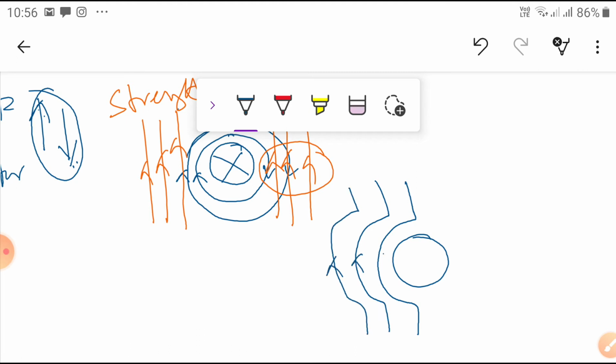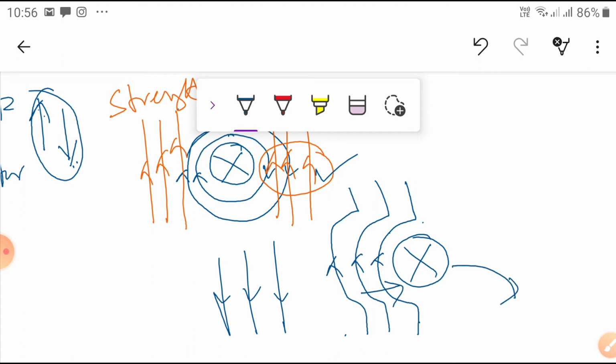So this direction, here the magnetic field is very less. Here they nearly cancel each other. We know that all these magnetic fields are like stretched rubber bands. They always try to stretch only, so they try to become straight in this direction. Whatever conductor is in between the stretched lines, it will try to move in this direction, so that these fluxes become straight only.